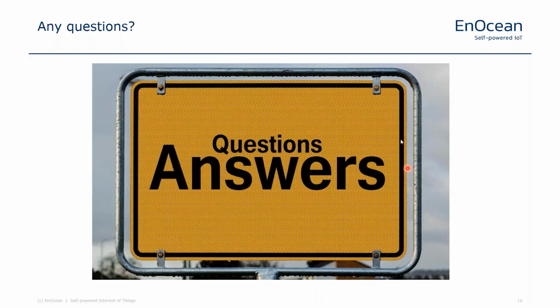One from Detlef, about lux in rooms: if the sensor is mounted on the room ceiling instead of the wall, will it work at less than 50 lux? Okay, I have to guess a little bit about the question because I see it is not complete. So yes, it's different. The best site for installation of solar sensors is the wall quite near to lamps or the windows.